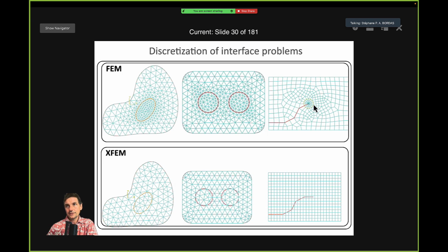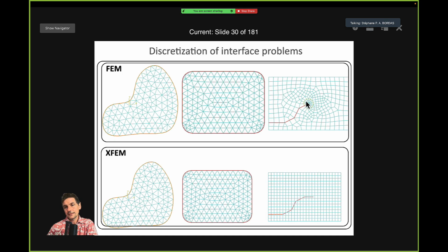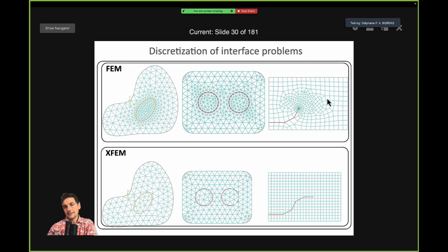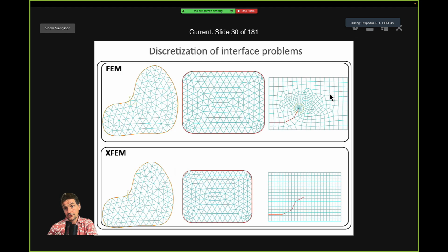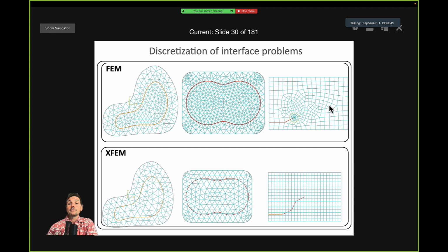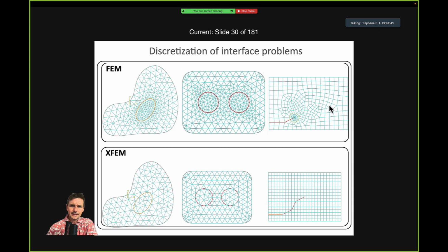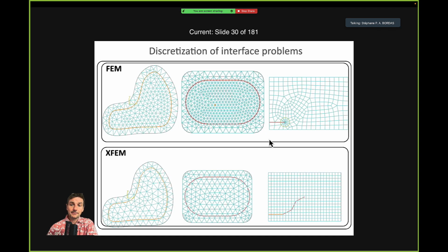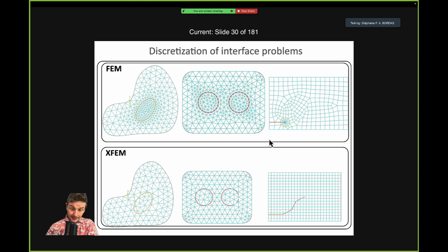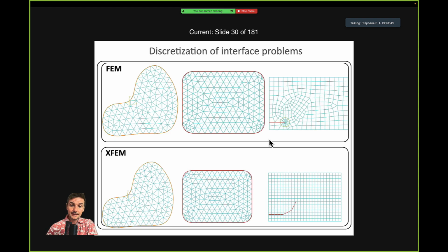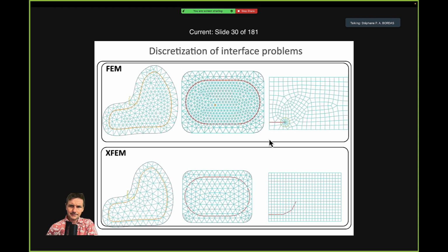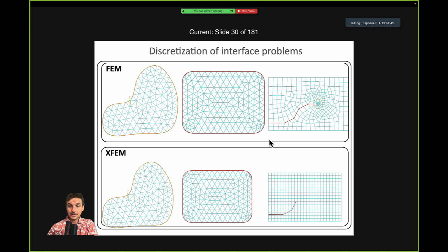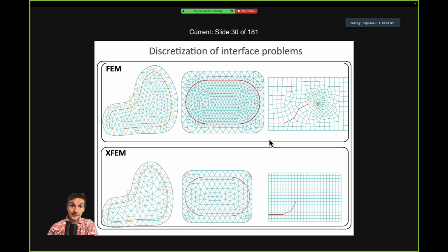On the right-hand side, you see a crack, and the crack is moving with this little rosette around it, which is fixed itself, but it's being attached to the surrounding mesh. So this is beautiful, but it's also very costly, in particular in terms of remeshing. And it's sometimes almost impossible to remesh in 3 dimensions with all these cracks propagating and coalescing. You can imagine the complexity, because you get very small elements, and generating these meshes is not feasible in finite time in general. So we cannot know.